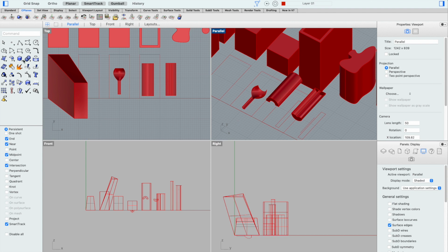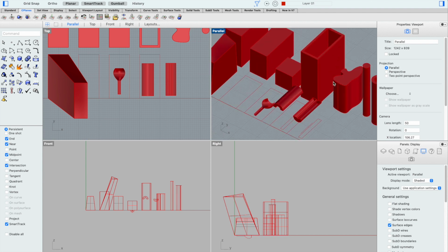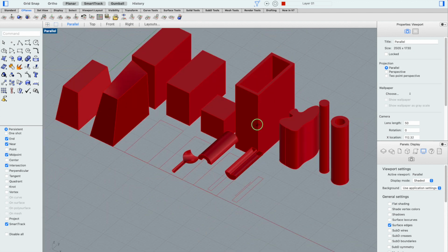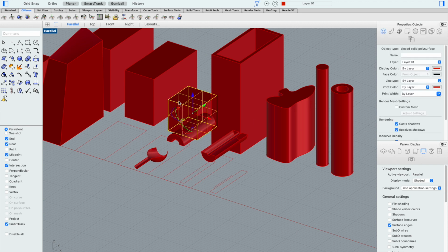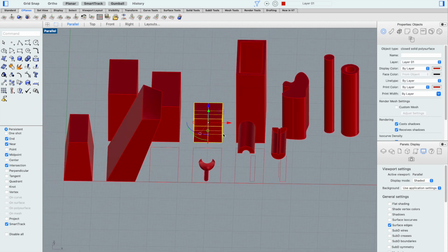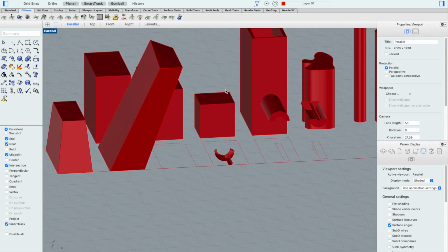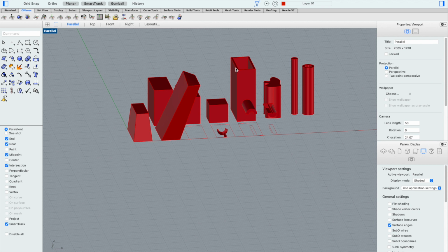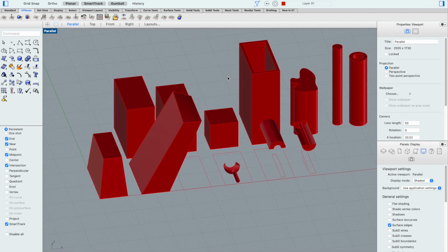The other thing I can do is use the move button to accomplish the same command, or I can use another preferred method and use objects as reference points. So let's say I wanted to move this box from where it is now, kind of at the bottom level with this other thing, to the same spot except moved vertically and level with the top of this box. No problem. I'm just going to use that box as a reference tool, and I don't need to know how tall it is. I could figure out how tall that box was and say, all right, Rhino, move it whatever that number of inches is.